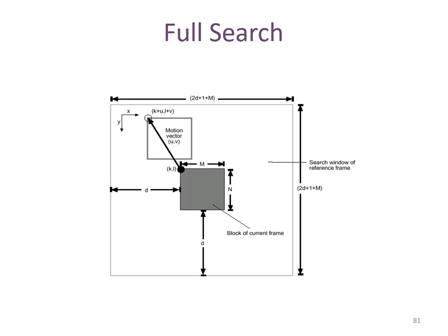So we don't have to search the whole previous frame. We can define a certain range, because within a very short time between neighboring frames, the motion vectors will not be that large. Okay, so we can define a reasonable search range here. Then we search all possible microblocks and compare the difference.